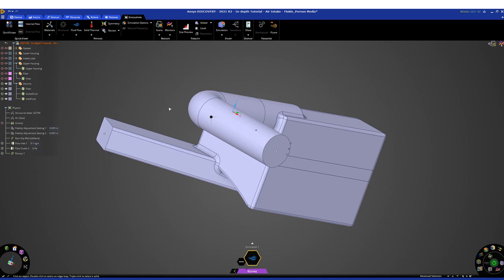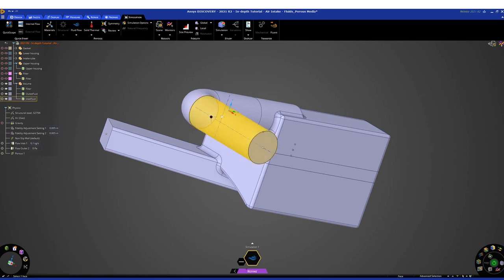So to add the monitor points, we use the halo again, but here selecting monitors, and then we just select the outlet surface, which we want to monitor the velocity on. So I'm selecting here the velocity and then average, which is the area averaged velocity on this plane.